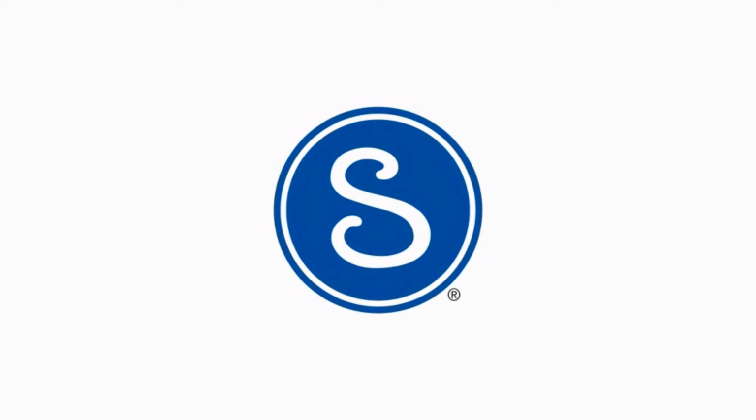That arrow is there to allow you to select which of the 2 sources is primary. However, you do not have to operate that handle in order for the changeover action to occur. Once you've selected the primary source, you walk away and when that primary source reaches the changeover pressure, it'll automatically start drawing from the secondary source. You do not have to intervene. Okay, that's great. Thank you.